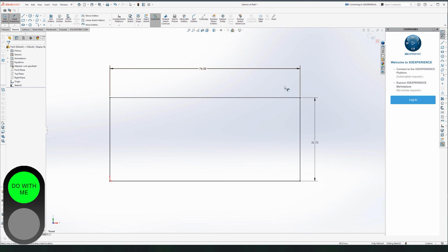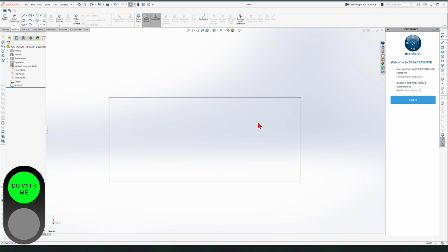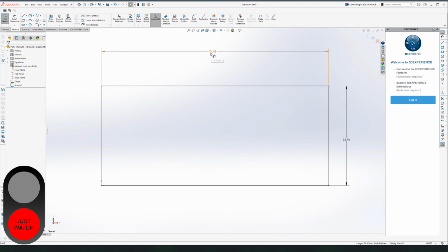It's easy. We move our mouse cursor down here where it says custom or otherwise. If you open it, you see I'm on millimeters, grams, and second. If you're on inches, pound, and second, change that to MMGS, which is the same thing as my custom. Do it on MMGS. And doing so jumps out of an active sketching mode, like this one right now. So we're going to go back in there, double click on the sketch, and make sure we have 74.52 millimeters and 32.6952 over here.